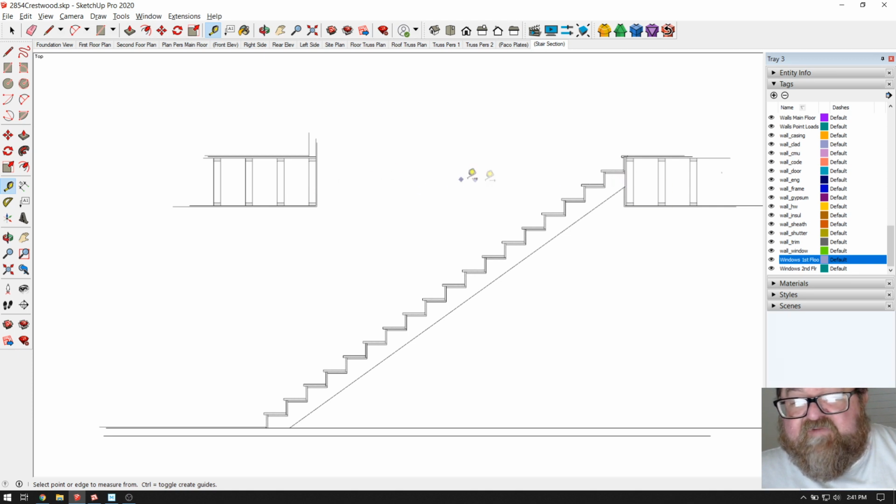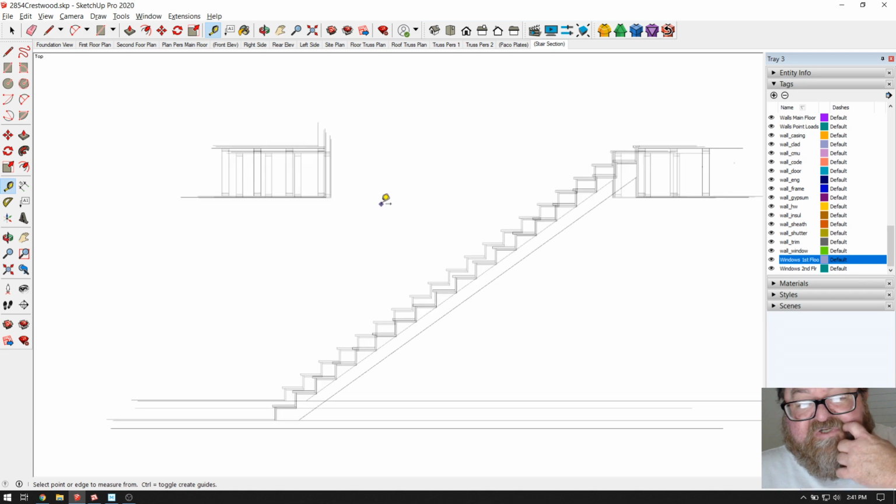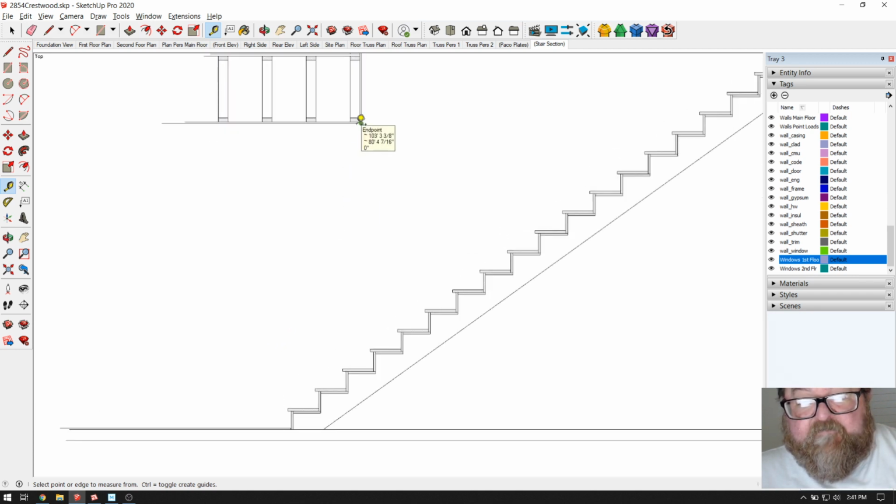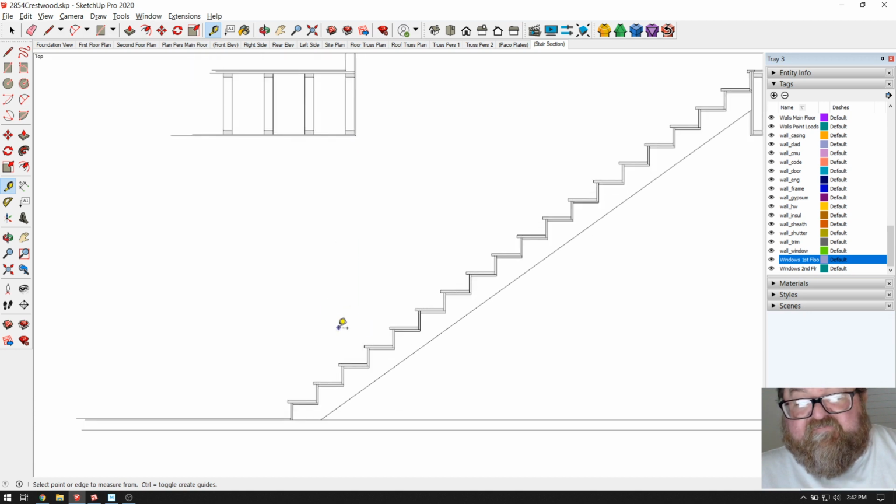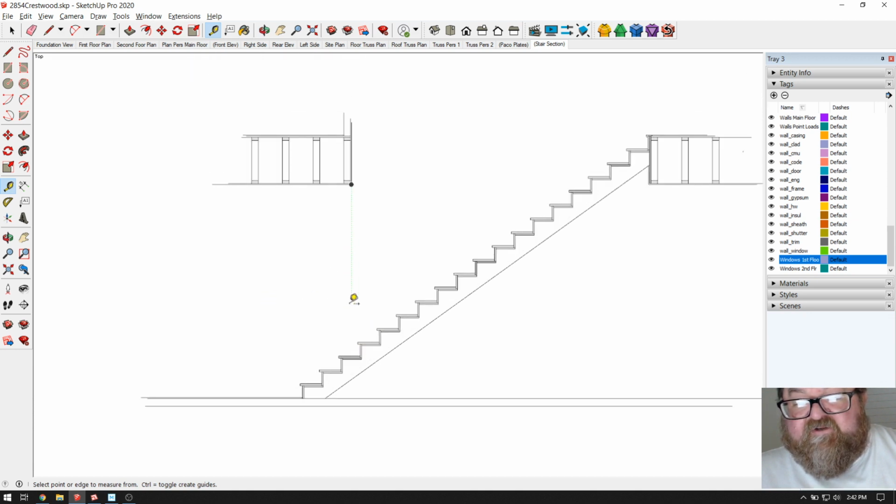Pre-planned out, having that opening that wide based on this amount of headroom here, which we get to measure to this stair. It's 7 feet 5, and even if the building inspector wanted to be mean that day and measure to that tread, we still have 6 foot 10, which meets code, which is 6 foot 8 in the clear. I like to have 7 feet because I feel like that's a better clearance.